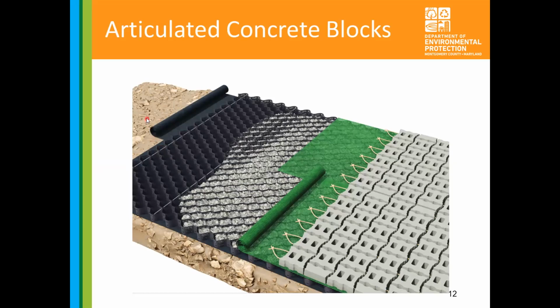As you see up here, this is where the existing ground would be, and then there's a layer to separate the stone, and these are going to be stabilized in these cellular, honeycomb kind of compartments. That'll provide some structural integrity and also assist with drainage. And there's some other design aspects to why we include this layer in terms of the shears and velocities, which we'll get into later.